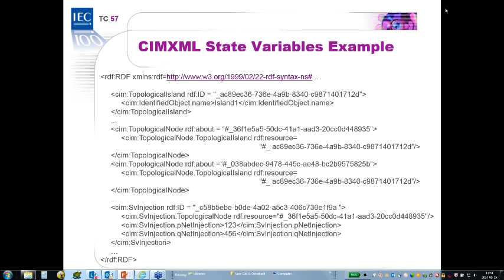The other way to deal with it is to allow for different voltages to some extent. And I think in the profile we say that variation of 5 to 10% is allowed. And as long as you know the voltages used on both sides, when you do the per unit calculation later on, you will get it right in the end anyway.